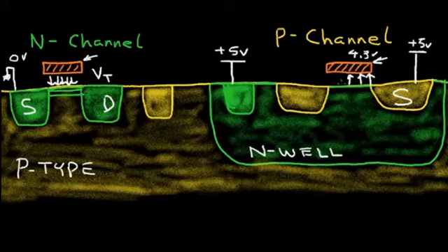So the electric field is from the positive voltage to the negative voltage. And at this point, the gate voltage is more negative by about 0.7 volts. And let's presume that the threshold, the VT, is 0.7 volts. So our channel inverts at the surface here. It changes from an N-type material to a P-type material, and we start getting conduction from source to this drain